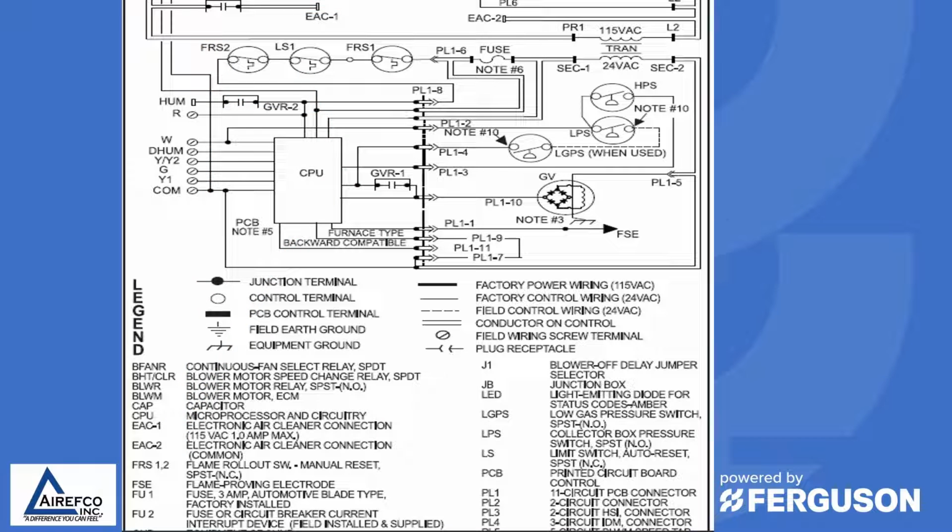When troubleshooting a safety circuit, the best way to do that is to check continuity through the safety switches to make sure that they're all closed. But one thing that technicians overlook most times is that there could be an open circuit throughout the wiring on the safety circuit. Where the safety circuit plugs into the control board is where you need to double check and make sure that you have continuity through the system. By taking your voltmeter and putting it on both sides of the safety circuit, you can check and see if there's any opening in the wires or the connectors or the plugs, so that you can detect that, troubleshoot it and take care of it.